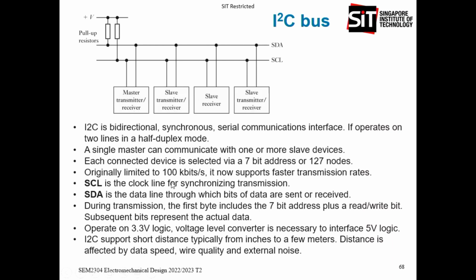I already mentioned SCL, SDA. During transmission, the first byte will include the 7-bit address. So you put in the address, then you put in the actual data.